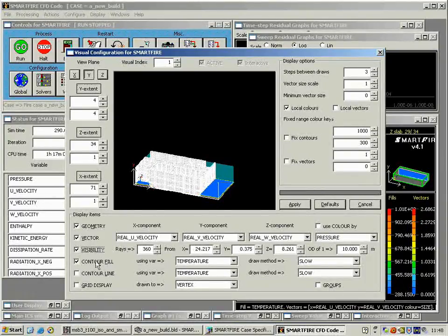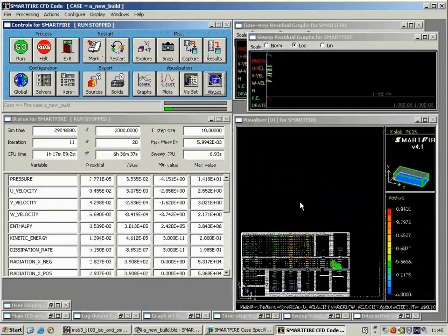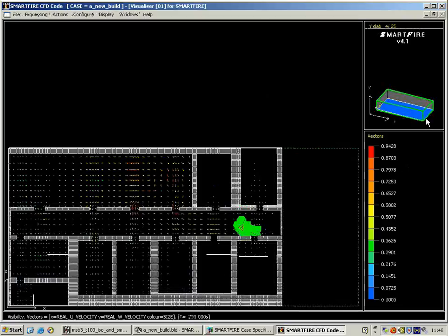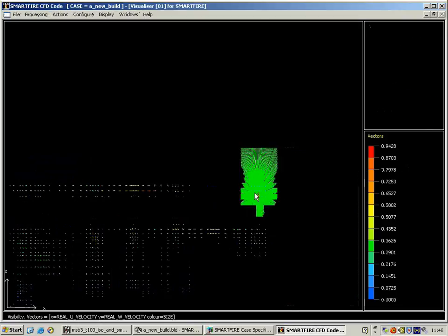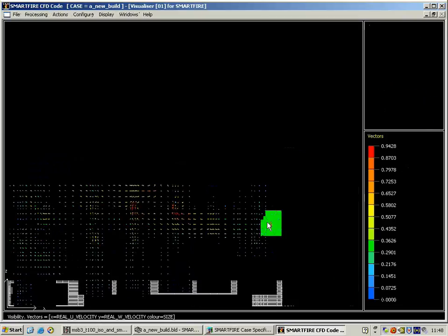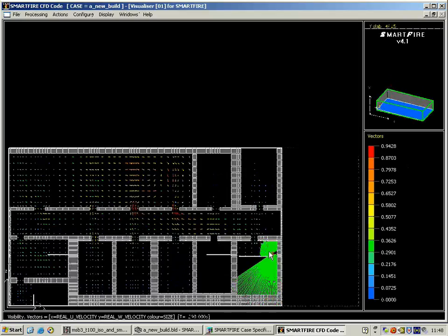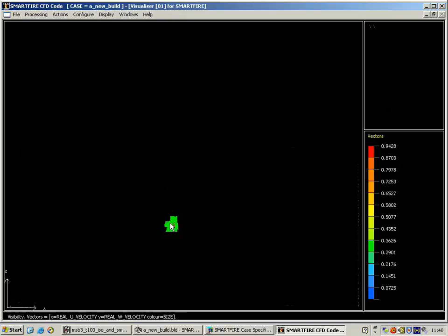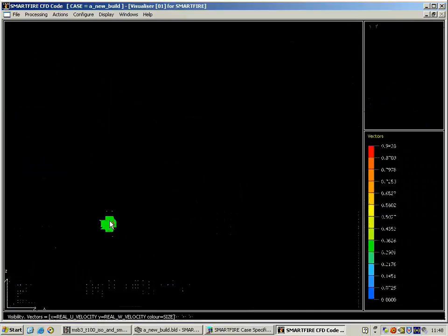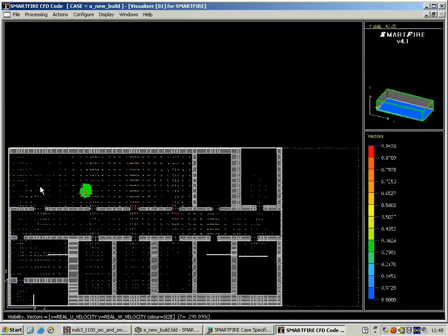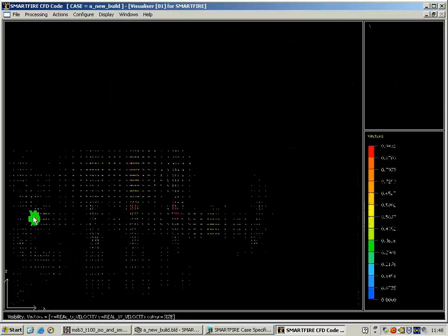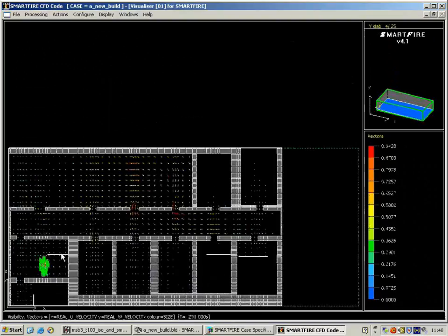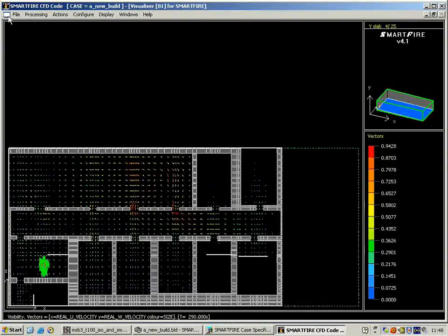And I'm going to activate the visibility tool, which allows you to interactively check out the visibility distances on a particular plane. Here you see I'm moving the eye tool around, and the green rays show how far, in theory, I'd be able to see. On this fire plane there's an awful lot of smoke, so I'm not able to see very far.